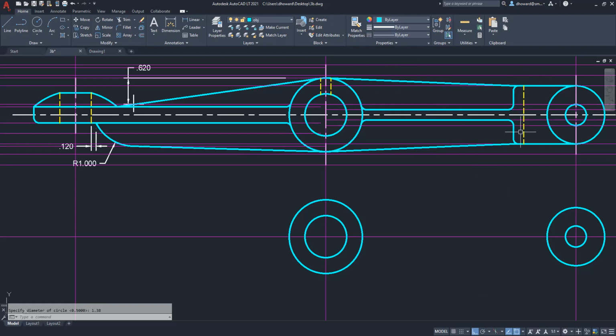There's also a fork on the end here. And in the top view, you can see on your drawing that this is basically a Y shape, or you may call it a fork shape, a yoke shape. In any event, it's got a wall thickness of 1/4 inch. And so that's the distance between this hidden line edge and that edge. And its overall distance from the center line here to its outer edge is 1.5 inches.